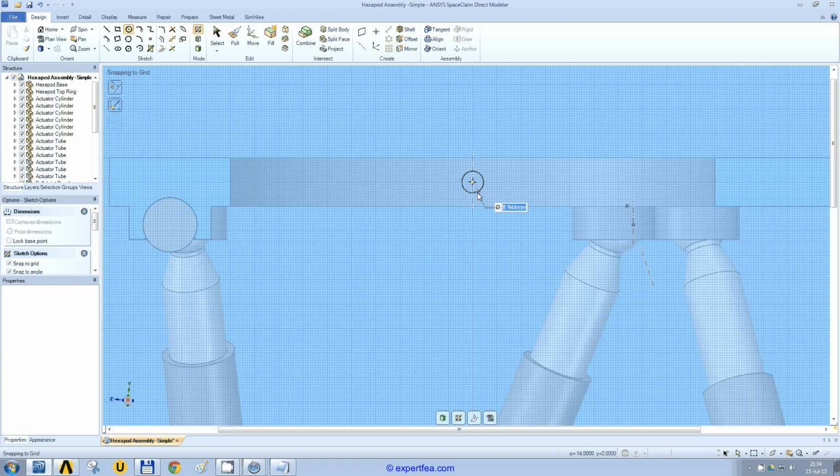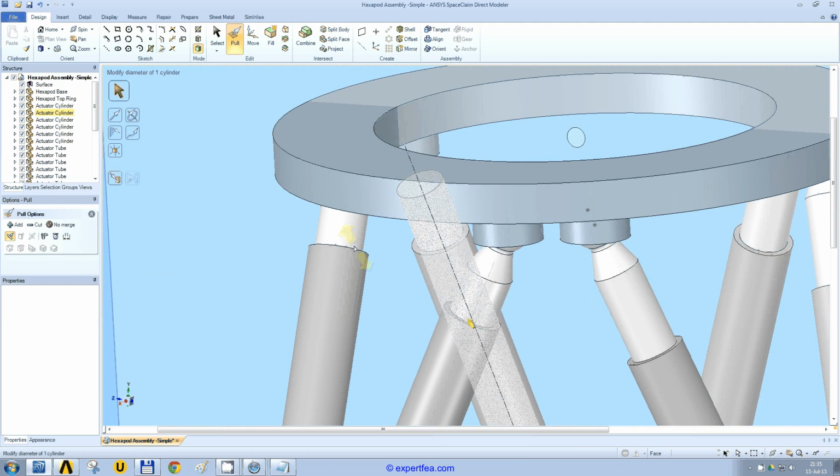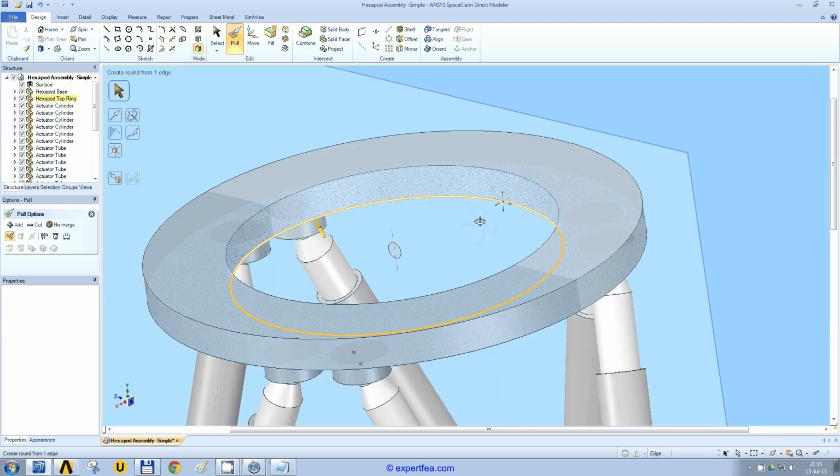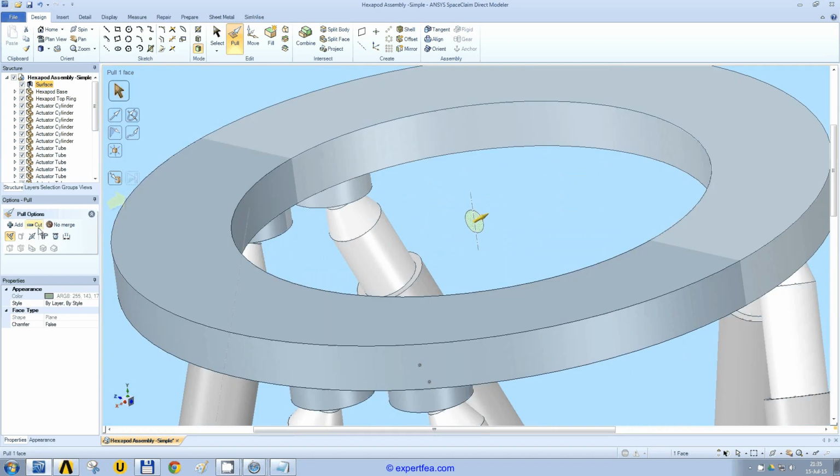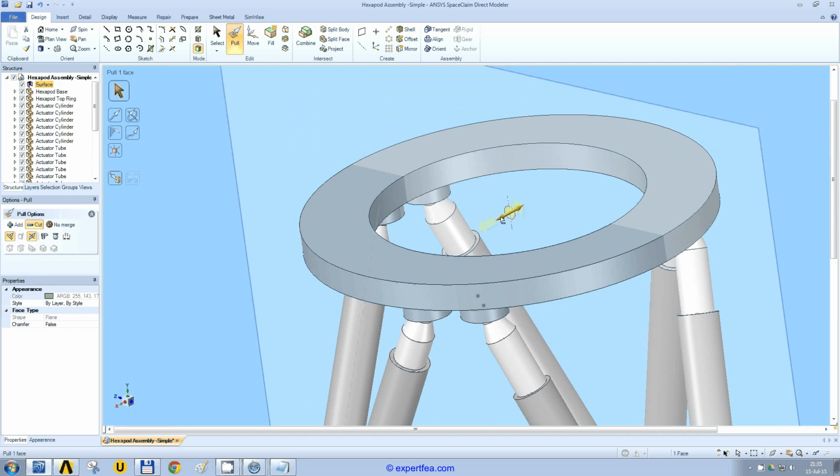We can be very generous. We can enter from the keyboard, let's say 10 millimeter. We return to 3D mode. We select this surface. What we need is to cut. We press the cut, and we press also this pull both sides, and we just pull from one of the arrows. Look, the hole is created.